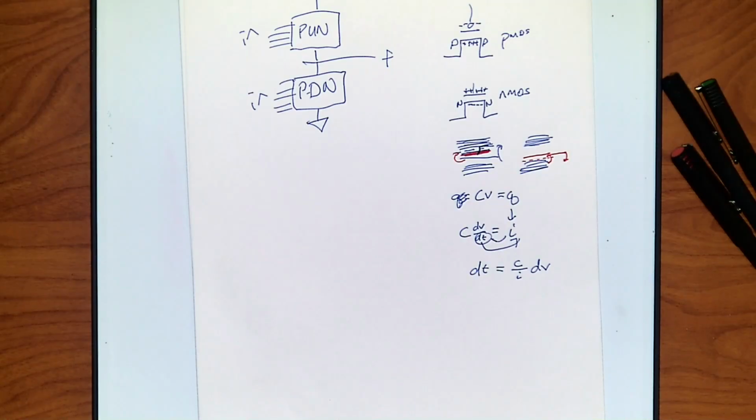Now, here's the problem. My charge carriers are slower, right, when I'm dealing with holes. So if I want to make up for the fact that they're being slow, it means they're not carrying things as quickly across the opposite side. So I need more, but to get more of them, you've got to make it bigger, right?